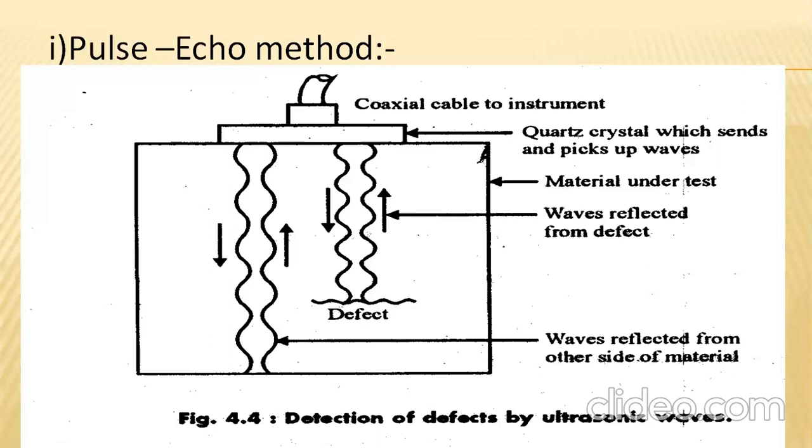Basically, in the ultrasonic testing process, we have two different types of techniques. The transmitting device is on one side and the receiving device is on the other side. That is one type of inspecting technique. The other technique is where the transmitter itself acts as a receiver also. Hence, we can say it's a transceiver. This plays a major role in identifying the heavy depth of objects. A greater advantage.